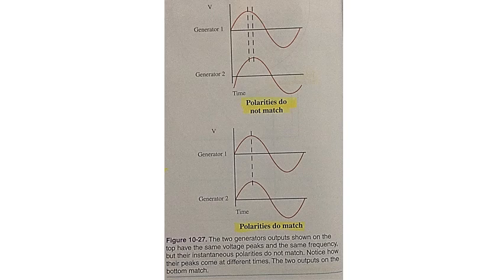The instantaneous polarities of the AC generators refer to that part of the sine wave that is represented at the output terminals of each generator at that instant of time. These outputs could both be positive or one positive and one negative. Ideally, if both sine wave patterns match, the generators have identical instantaneous polarity. These generators can be connected together electrically.